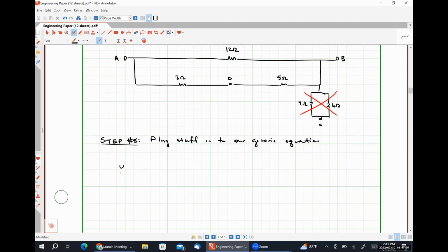So our generic equation should now be y is equal to y at 0 minus for t less than 0 minus, and y at 0 plus e to the negative t divided by tau for t greater than or equal to 0 plus. So this is the equation that works regardless of whether we have an RC circuit or an RL circuit. We just need to be able to remember how to calculate tau.